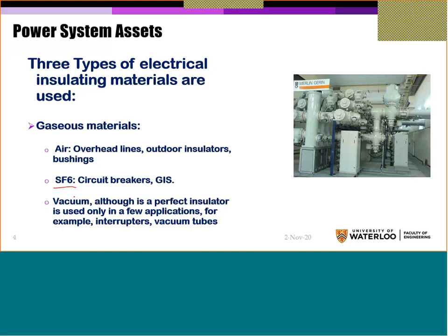If you remember from chemistry, once an atom absorbs an electron, it goes through what we call an excited state, and it stays excited until it releases the electron, so it becomes an unstable material. However, SF6 has the ability to absorb electrons and still stay a stable material.